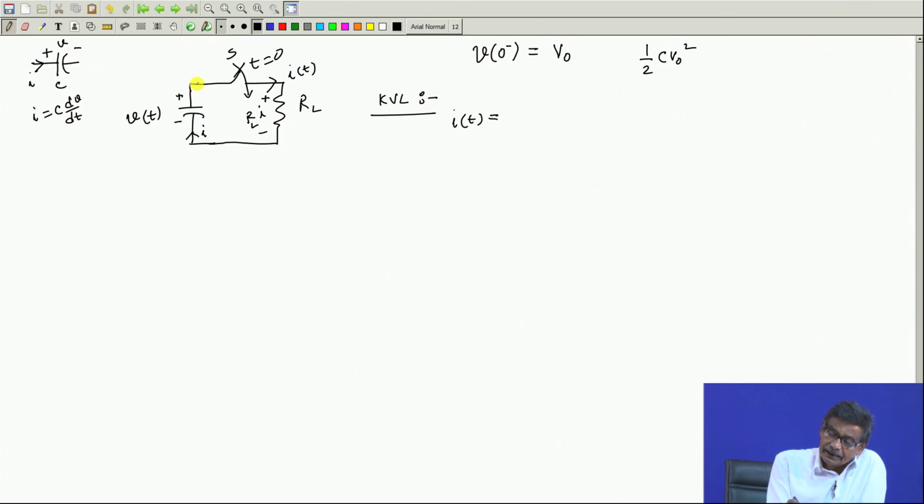Therefore, here the current is leaving the positive terminal, or I can say that minus I is entering through this plus to this place, is not, this is one and the same thing. So, I should write minus I, this step is crucial, minus I to be consistent with this polarity of this voltage current relationship of a capacitor. So, minus I is really entering, and this I can write it to be C dV dt.